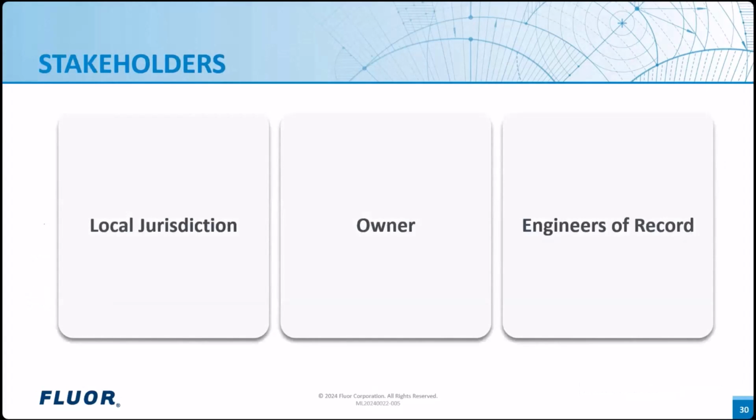Some local jurisdictions require a pressure relieving device, or other means are accepted only upon approval. They may require a justification for why a PRD, or pressure relieving device, cannot be used. Even though economics and schedule are intimately tied to practicality, some jurisdictions may not be swayed by purely economic and schedule considerations. It's always better to frame the opportunity for HIPPS in terms of impracticality.